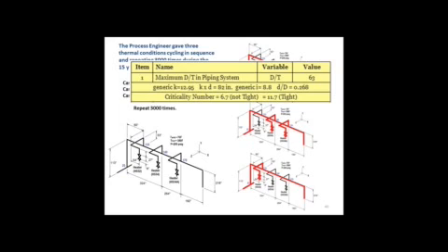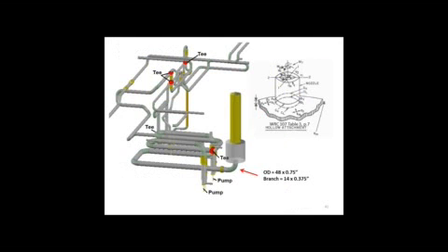So if we do the criticality analysis on this, if I considered that the system was not tight, it was 6.7, which is just over 5, which says, well, maybe we're interested in it, maybe not. But if we considered a tight system, the criticality number goes to 11.7, which says, yeah, you might want to think about that. So we can see that the criticality constant is definitely affected by the tightness of the system, and we want to get a good sense of when systems are tight or not, because the stresses will be significantly affected by those things. Let's go to the next system.